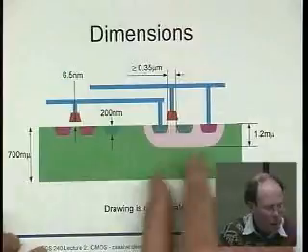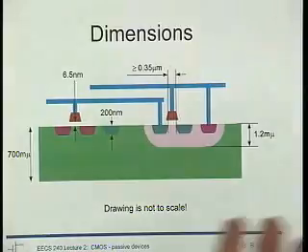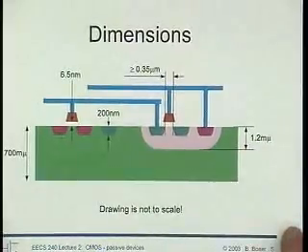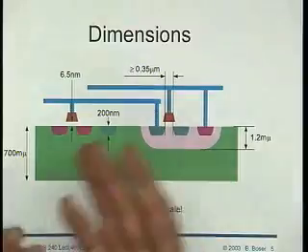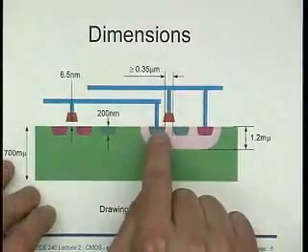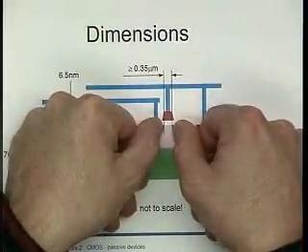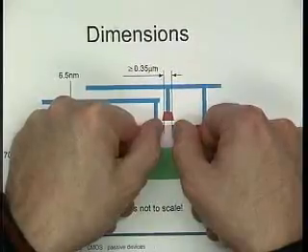So there is the well. The well actually goes relatively deep, maybe a micron or so. Again, as we progress to shorter channel length devices, that dimension also goes down. Used to be 5 micron. The junctions themselves are fairly shallow, a couple of tenths of a micron or so, and their depth has to be in some relation with the length of the device. The length of the device is the distance between the source and the drain, and the minimum in our process for 240 is 0.35 micron.